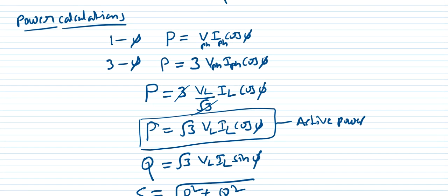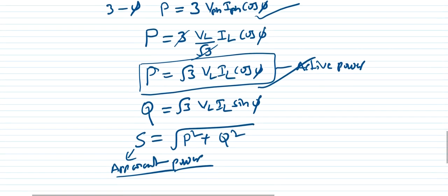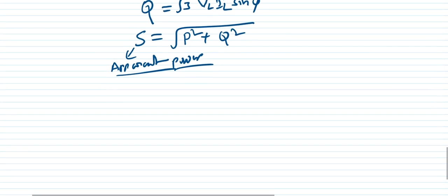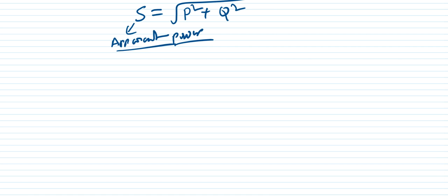So for a three phase circuit, this is the power calculation in terms of phase voltage and phase currents, and this is the power calculation expression in terms of your line voltages and line currents. So this is how you can understand the star connection supply system of the three phase AC system.